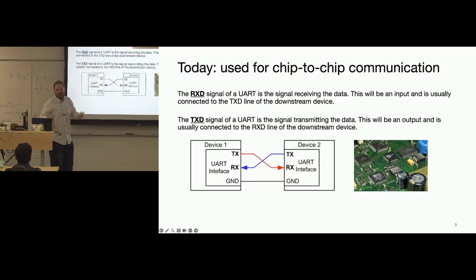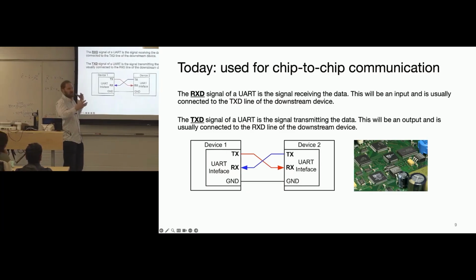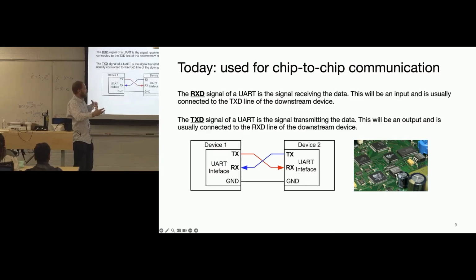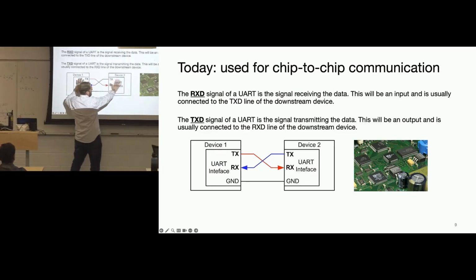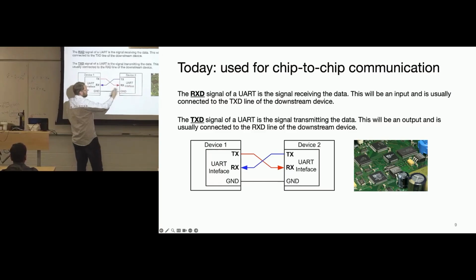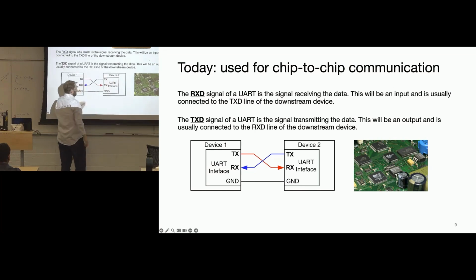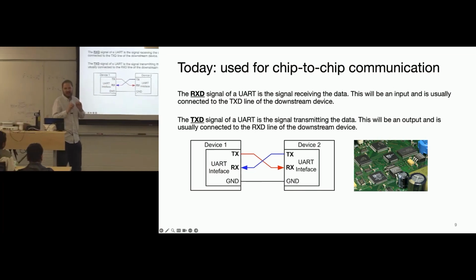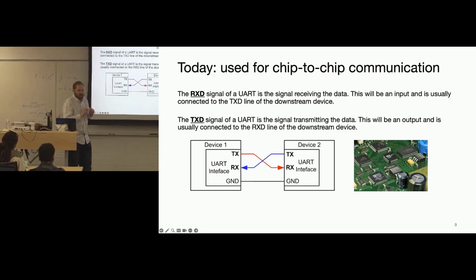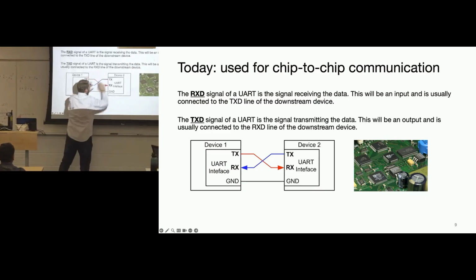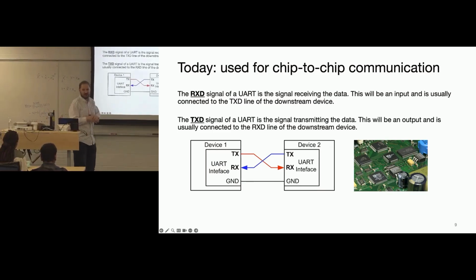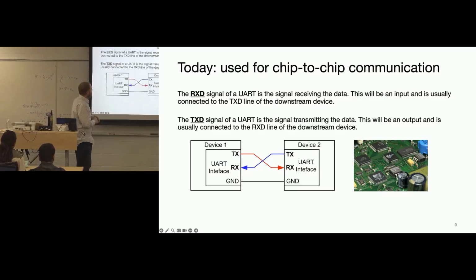But that's not the perspective about how this protocol was made. The perspective was that there was no master or no controller. These devices were the same, they were equal, right? It was originally made so computers could talk to each other. And so now, from this point of view, this is the controller, right? Transmit, receive. So my suggestion is, if you're confused at all, on your board, leave yourself extra little pins so that you can manually rewire that if you screw up. Or there are little tricks you can do with 0-ohm resistors, so you can put the resistors this way or that way to connect different things and save yourself the embarrassment that I had of getting it wrong.